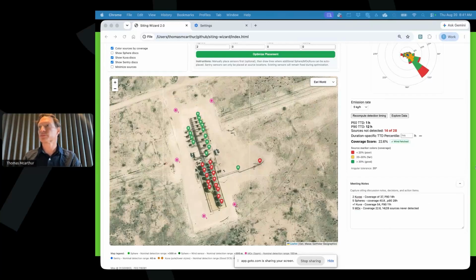Okay, so what coverage should I target if I want to achieve site level reporting, OGMP 2.0 level 5 reporting? Generally that should be around 30%. There is some math behind it that, as I mentioned, does extrapolate beyond what is detected and quantified to the times that we know we don't detect it. So that's kind of the flip side of this. There are times that a site will not detect things because the wind is not blowing in the right direction.